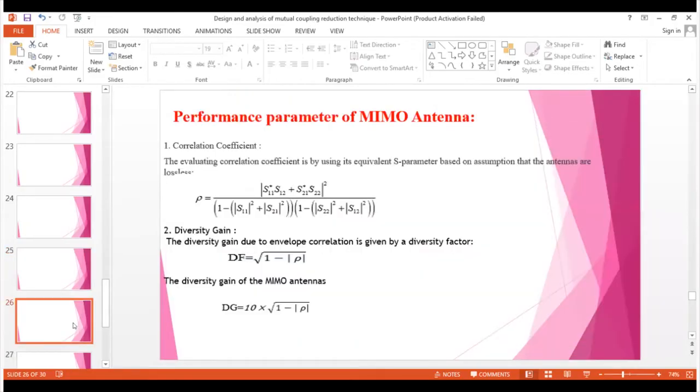These are the performance parameters of the MIMO antenna: the envelope correlation coefficient and diversity gain. For ECC, the estimation for 3D radiation patterns of the antenna, ECC can be calculated from the scattering parameters or the radiation pattern of the antenna. It will be a standard at 0.05. And for diversity gain, the effect of a MIMO antenna heavily depends on the diversity. The relationship displayed below can be used to calculate the diversity gain of the antenna. The diversity gain is 9 dB for 2.4 gigahertz.